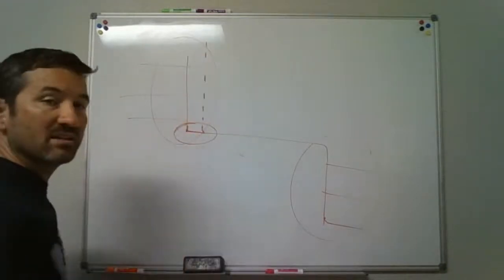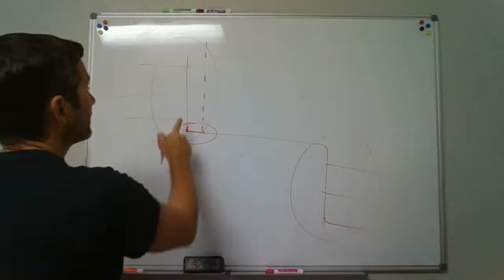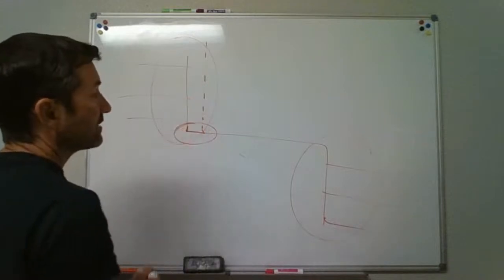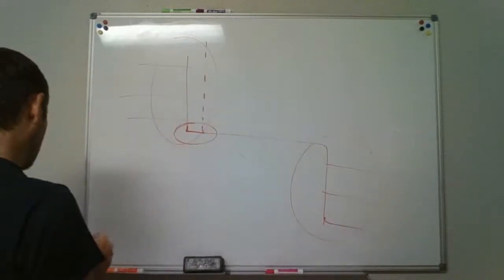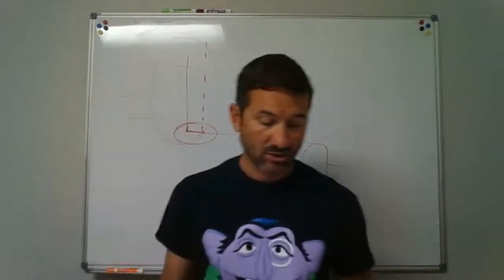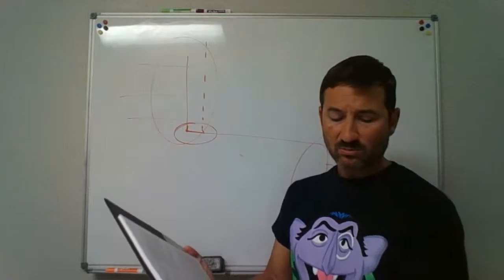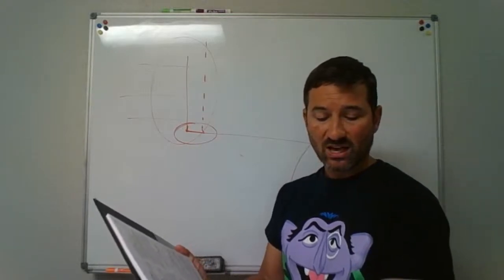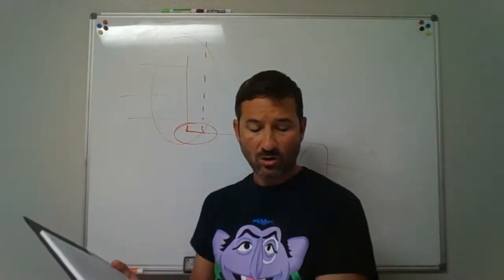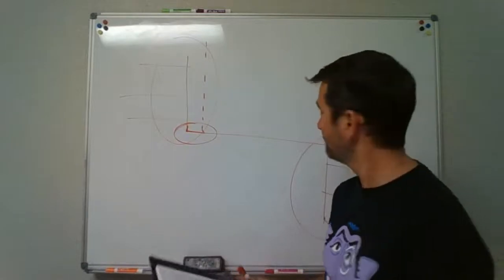Within 10 times the diameter of the stack is going to be the connection of this vent stack there, and you're going to vent both the upper and the lower. The lower section of the drainage stack should be vented by a yoke vent connecting between the offset and the next lower horizontal branch. The yoke vent connection shall be permitted to be a vertical extension of the drainage stack.